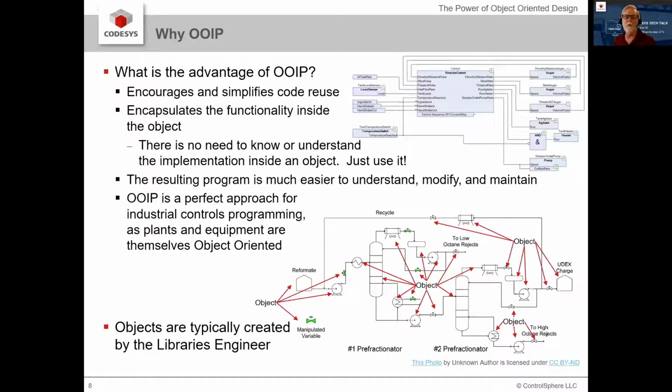In software terms, this is known as encapsulation. Everything that is required to control a motor is encapsulated inside that motor control block. Just drop it into the design and it works. Just as a plant or equipment designer doesn't need to be an expert at motor design to specify and install a motor into his or her plant, the control designer doesn't need to be an expert in motor controls to configure and use the motor control block.